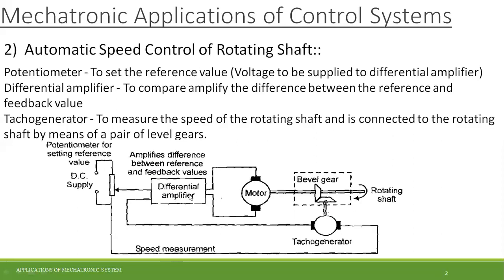And hence, to compensate for the required rpm for the actual work to be done on an industrial basis, there might be an increase of the voltage power supply. That is nothing but the resistance value. By increasing or altering the resistance, we can control the rpm of that particular motor, and how much rpm we need to set can be identified with this contact type tacho generator, which is already giving the feedback signal to the differential amplifier. That is the main concept here.